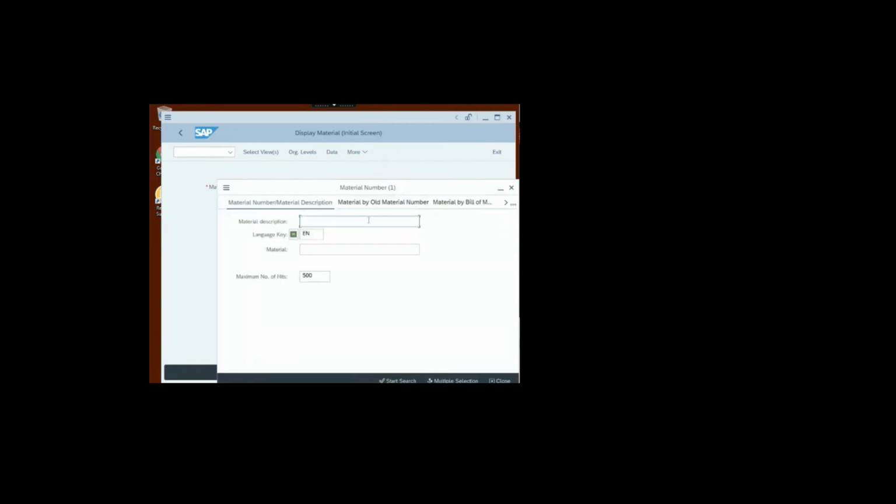Now material, click on material bar, the third bar. And then asterisk key. It's number 8 for me. So shift 8. Okay, and then dash 172. Hit enter.